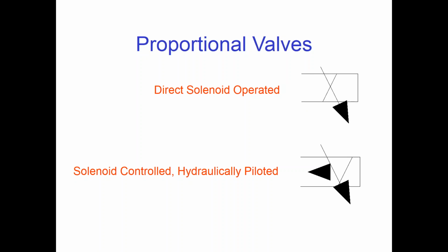Long years ago, the only real option we had for that was a very expensive servo valve. Proportional valves started taking that over. They're not as accurate as a servo valve, but every year I see them get more accurate all the time. One of these days, they'll probably completely replace servo valves, but nowadays we only need to use the very expensive servo valves and deal with the maintenance nightmare of keeping the oil so exceptionally clean because of the tight tolerances there, when we need very precise control.